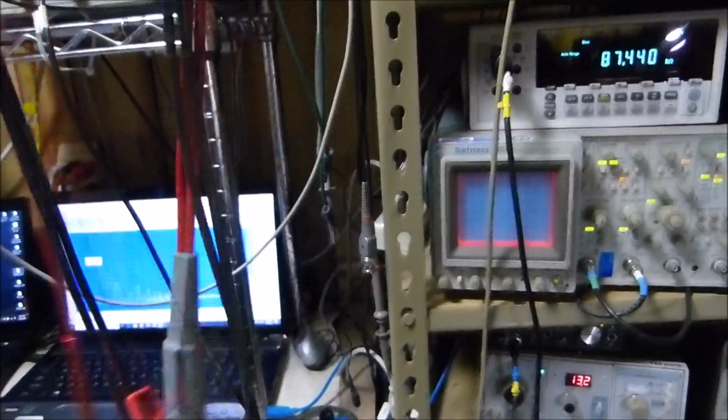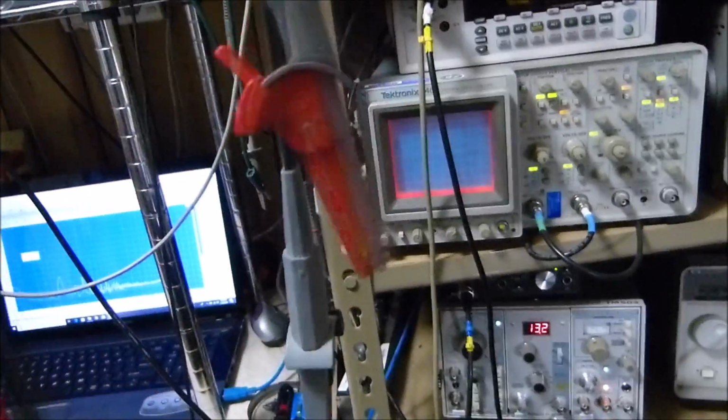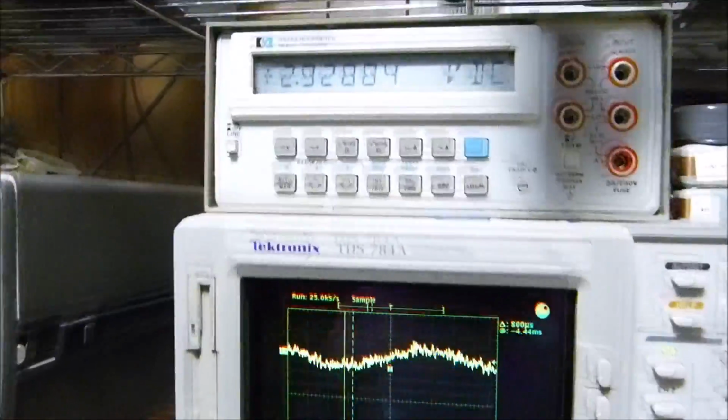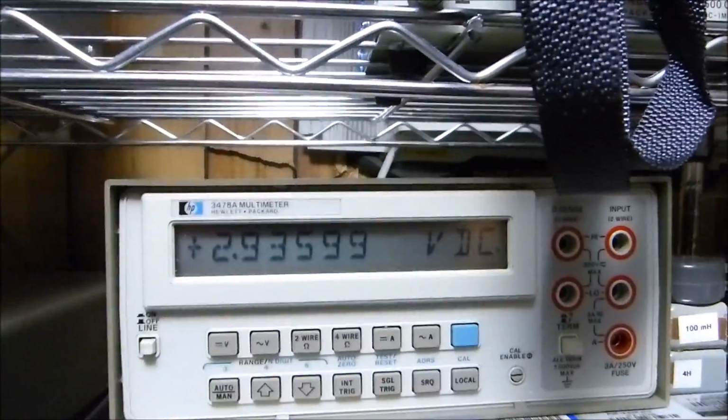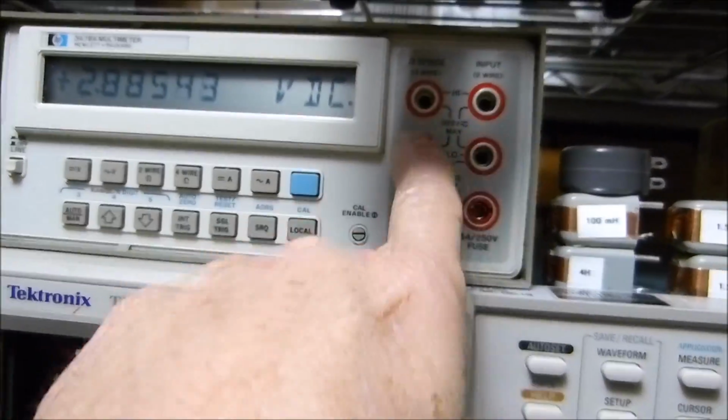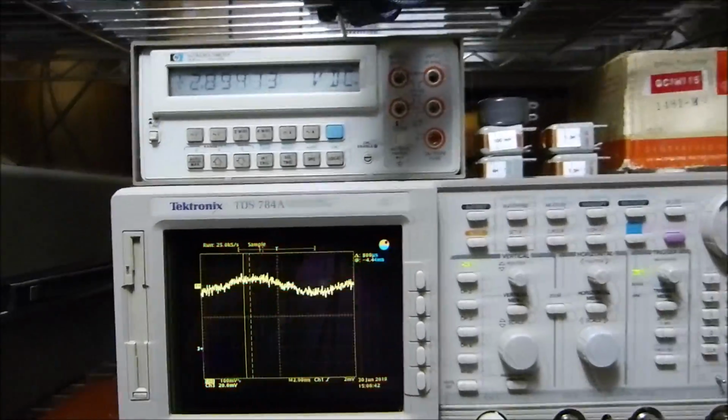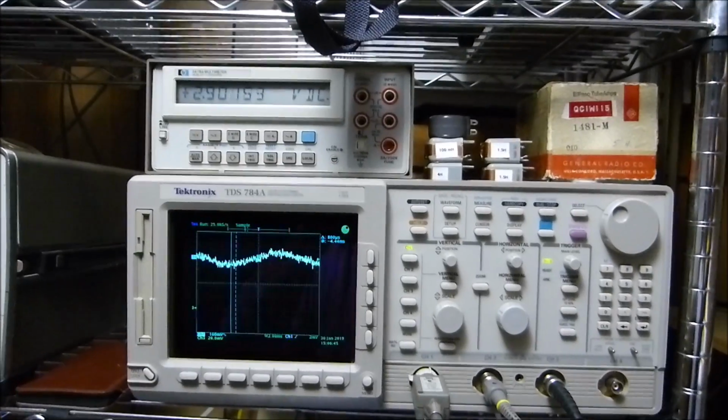And what it does is it puts a voltage out to the tips of the probes, and then it measures it so that you're not measuring the resistance of the wire. This little HP up here does the same thing. It's got 4-wire Kelvin probe type connections into it too. You do want that if you want to measure low resistance.